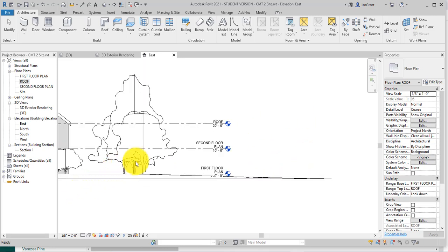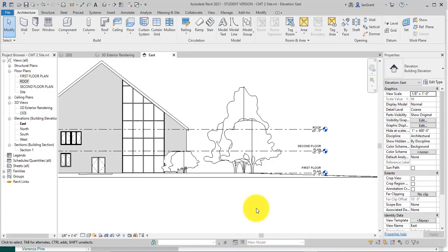So what we need to do is to establish here a foundation level that we can use to place the basement floor. To keep things simple, we'll go ahead and create a level that's -9 feet for the basement floor, keeping in mind that you have the structure itself of the floor, and we'll come back to that when we create our wall section.